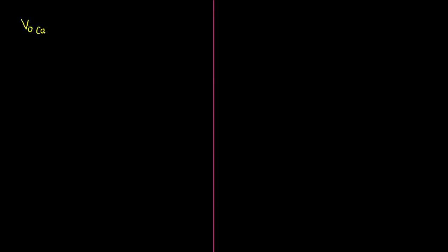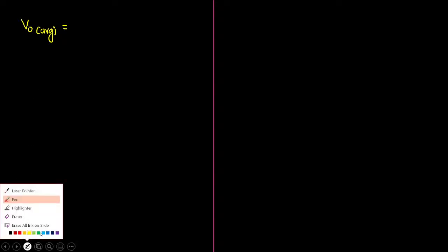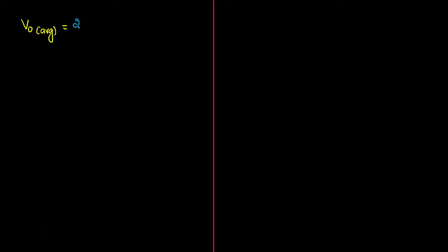So, the value of V0 average can be written as, without inductance, you know how to write, 2Vm by pi into cos alpha. With the source inductance, I have to put minus. I'm just subtracting the effect of inductance here. So minus, the same 2 by pi.